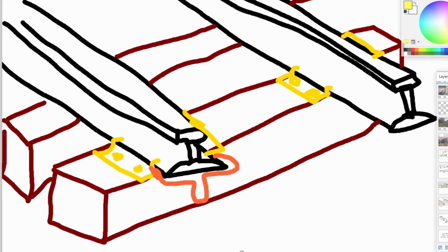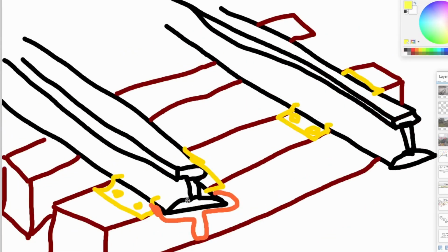We have ties. Ties tie the rails together and hold them in place, and we have special devices to help us do that. We have tie plates that help distribute the force from the train to the tie, and they also help locate our spikes, and the spikes hold the rail and tie plate to the tie. The ties are typically made of wood. They're typically treated with creosote to make sure that they last a long time and also can accept the forces from the rail and the tie plates without wearing excessively. We also have rail anchors that prevent the rail from moving longitudinally down or up the track as the train imparts force to it.